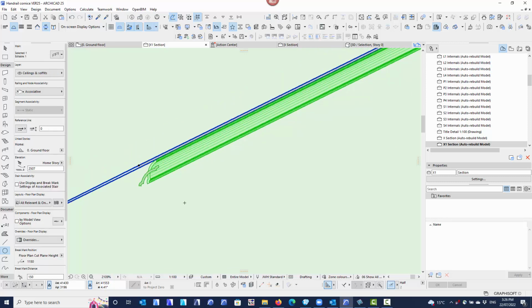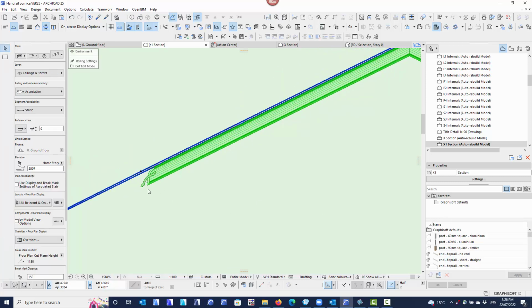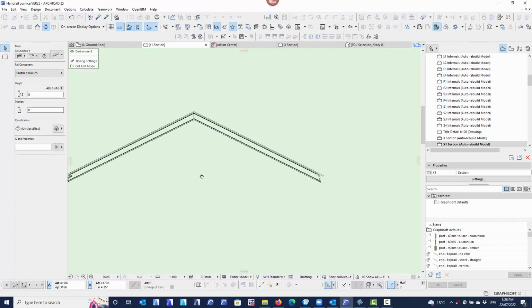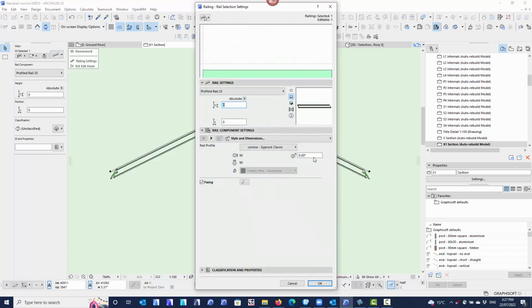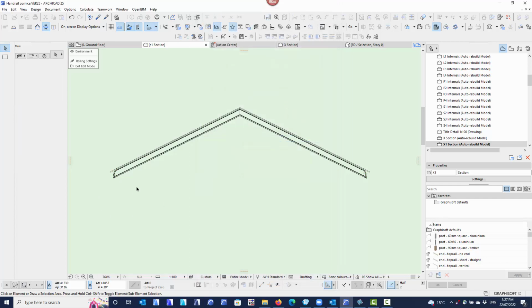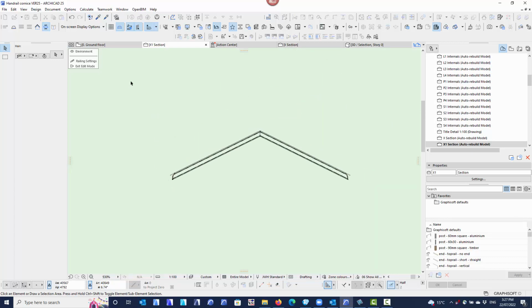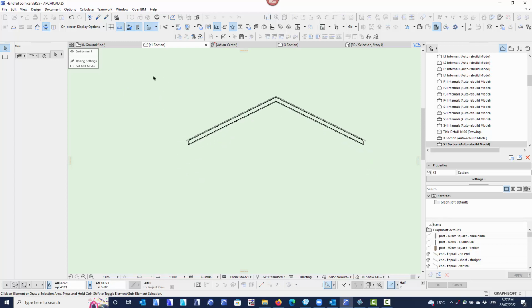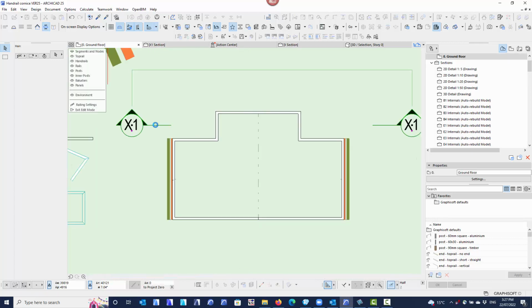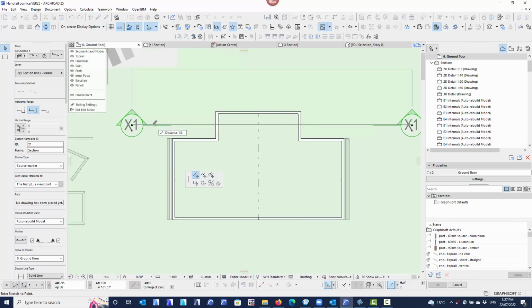So there's my ceilings. The first thing to do, go into edit mode, grab that cornice there, grab that cornice there, go into my settings, and remember it was minus 25.63 degrees. That fixed that up, no problem. We've got the same issue in that I need to drag that down. Now, if I was clever, when I had the section back before, I would have just grabbed that circle. Actually, that circle should still be there.